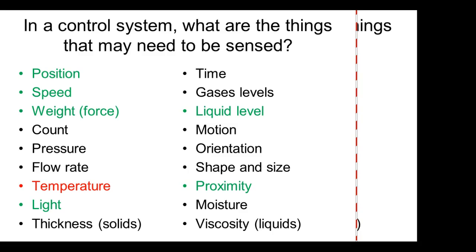Now they're actually starting to use it in robotics, where with these big robots, instead of caging them up, they put them out on the floor. And then they have a vision system up there that's monitoring, and if people walk into the range of the robot, it starts slowing down. It doesn't ever really stop until you get inside that restricted space, but it starts slowing down, and the closer you get to it, the slower it goes, until you get into the restricted space where it could actually strike you.